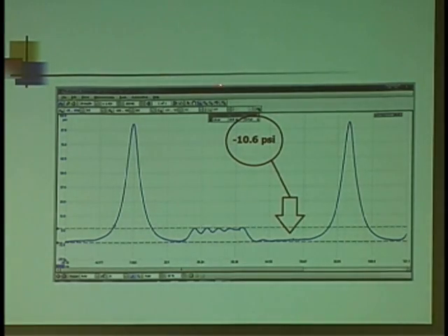Okay, so I get the TDC, the intake valve's open. Now I'm coming down on the intake stroke. And if I mark off those lines, and I'll show you in some notes here in a moment, I can use these ramps to help me gauge cam timing. Now, if we suspected there was an issue with cam timing, first we could see it in that ignition event, right? But what about multiple cam engines, or VVT?